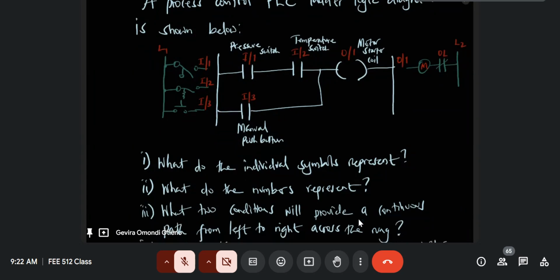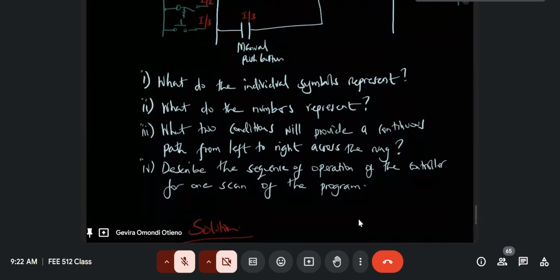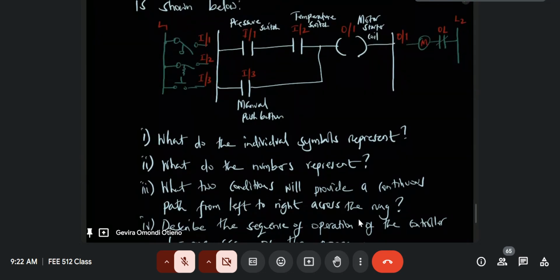That's why in our expression of human beings, we were using logic expressions, if A or B, you know, that is how we understand it. But the processor for the PLC understands those as expressions of instructions. So it's like, go to this memory location, take the instruction you find there, execute it, and then update the output.